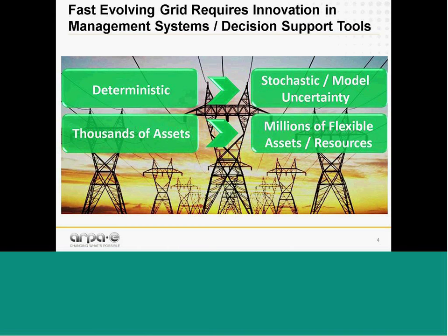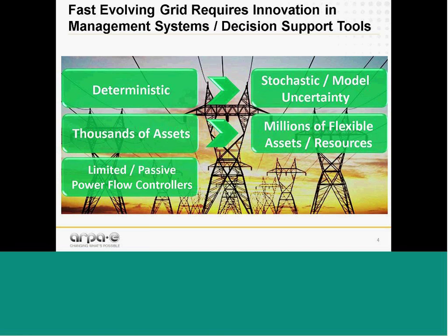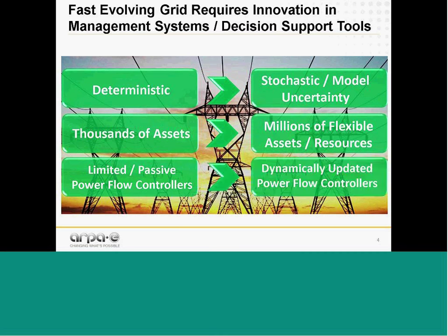It may not be a more efficient device itself in terms of a DER, but it can make or break a new technology being adopted. And another topic is passive power flow controllers or limited power flow controllers. You can create a new hardware component for your grid to help you manage everything from the dynamics to simply congestion. But until you put it into your modern management systems, it doesn't have a proper representation, you don't properly acknowledge it, you're not going to get the value out of it. So we're also interested in that aspect as well.